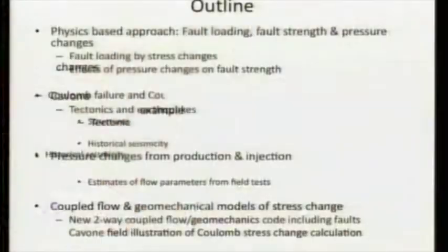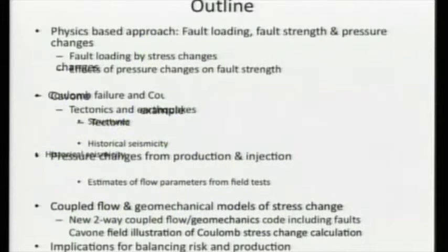We've developed a new two-way coupled flow geomechanics model that includes faults, and we are going to use it on the Cavoni field as an illustration of how quantitative, physics-based calculations of change in stress and strength on faults can be put into a reservoir context. And finally, we think the approach we've developed has very useful implications for balancing risk and production.